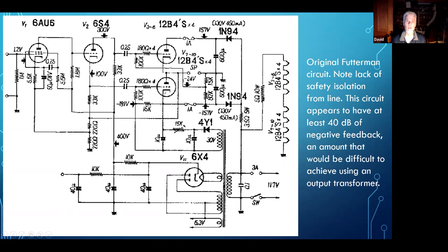There's essentially no voltage gain, and probably there's voltage attenuation in the output stage. And there's no voltage gain in this phase splitter stage either. All the voltage gain is in the first stage. And this topology offers some really important advantages if you want to apply a lot of feedback. The impedances in all this part of the circuit are low, and so the bandwidth is going to be quite high. The first stage has open loop lousy bandwidth.